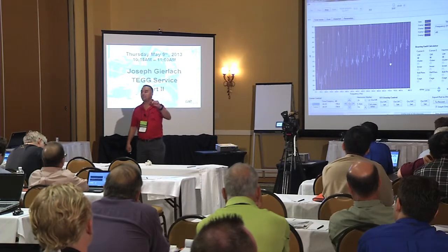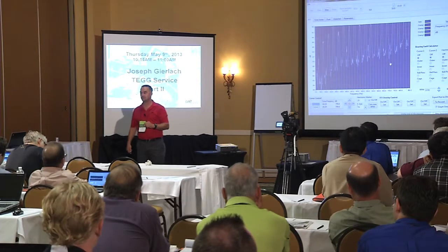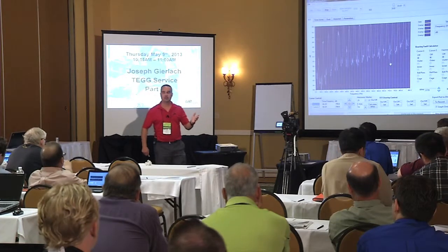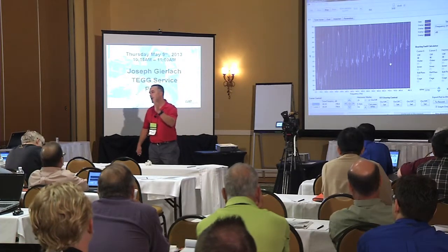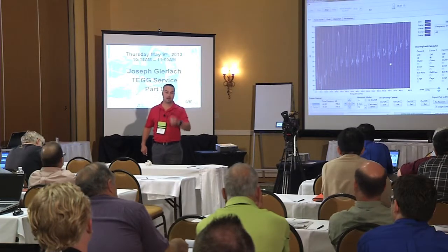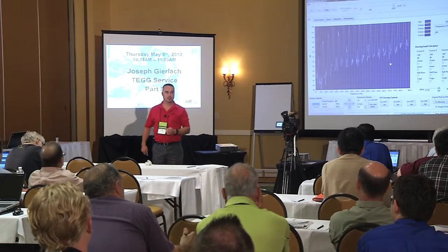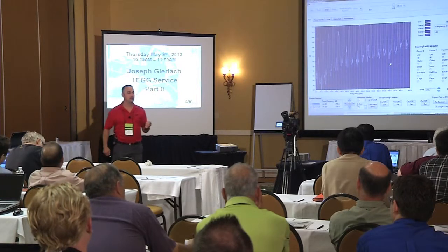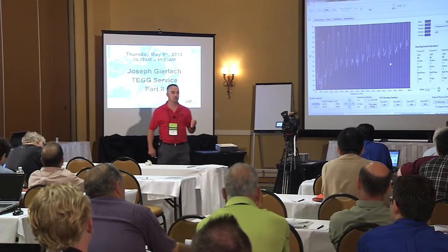Well, here's what it's not. It is not electrical. Does that make sense? This is a key tip-off right here. If you ever see a harmonic that's half your operating frequency, you can rule out electrical immediately. Because there's no way a 50 hertz system is going to generate a 25 hertz harmonic. But a mechanical issue will.